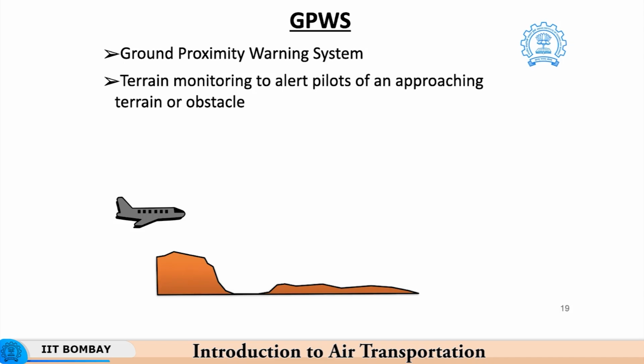It operates mostly when the aircraft is within a certain height above the ground level. Whenever such an altitude is reached, the GPWS system becomes active and carries out a regular monitoring of the associated hazardous flight conditions. Based on the presence of such a flight condition, the GPWS system will send a visual as well as aural warning signal to the pilots.